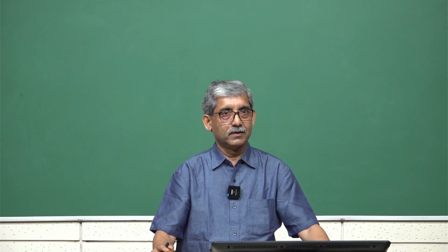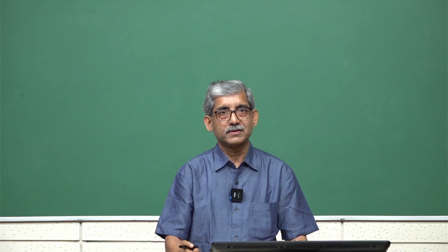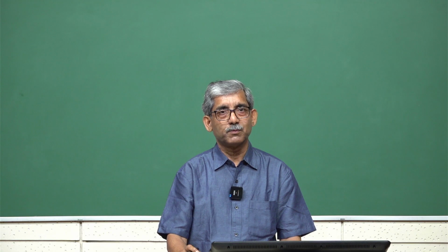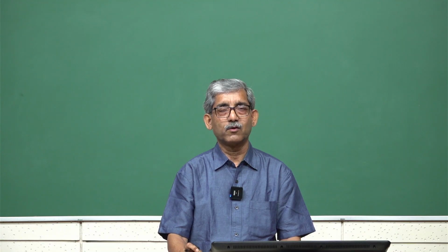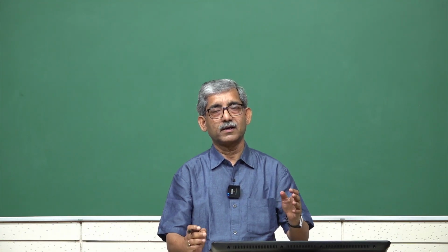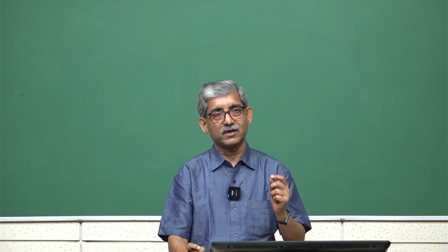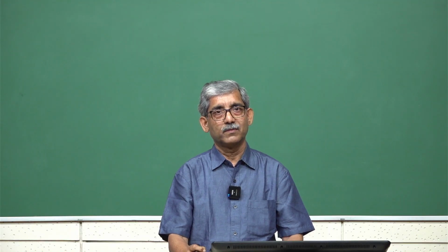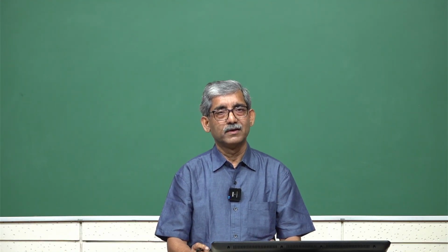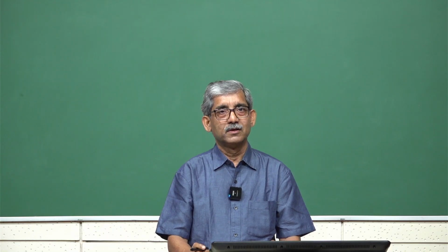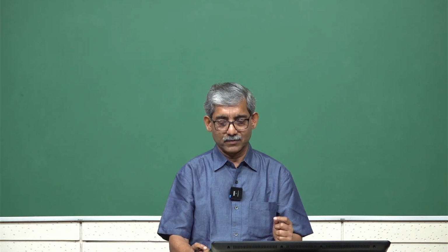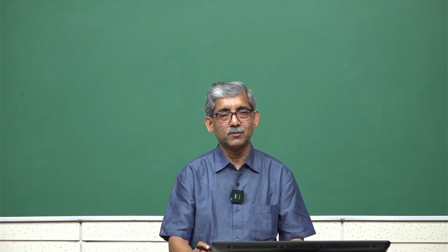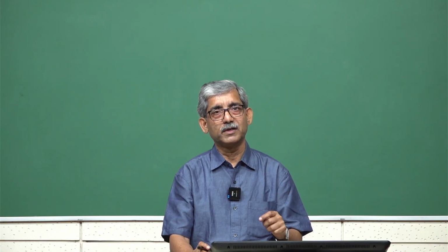Hello everyone. Now our present topic is the spinning geometry. In ring spinning, the spinning geometry plays an extremely important role in controlling the yarn characteristics, yarn structural parameters, yarn properties and yarn breakage. So, these are controlled by spinning geometry.